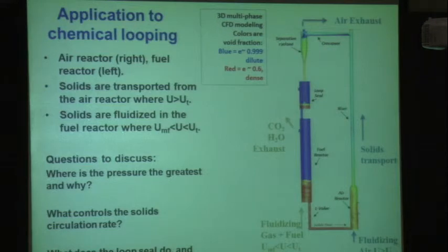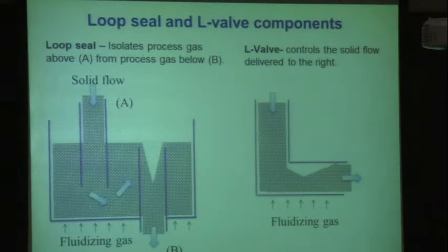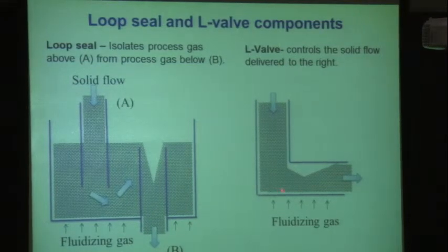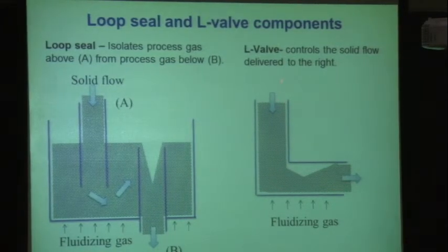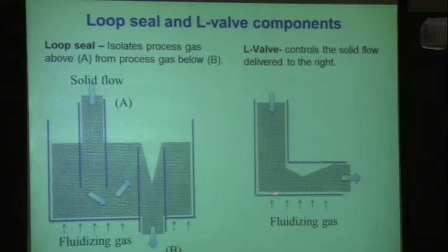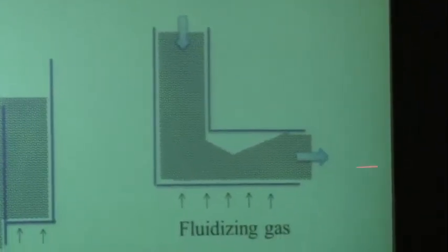And how do you do that? Well, that's that job of the L valve. These things look so simple, but man, they are really, really hard to get to operate. This is that bottom leg just shown really large. You have the solids coming down. This is the highest pressure point, so the material's trying to go that way.